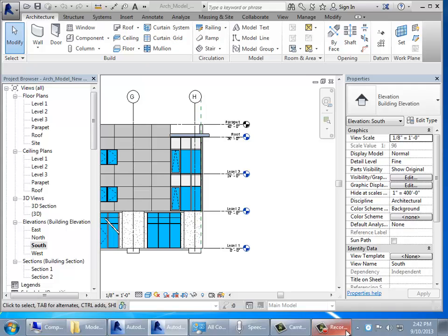I typically just leave it at 0 as a starting point, but it may be easier for you, since you're working off a set of drawings that are already referenced to a specific elevation. You put it at 100. There's nothing special about the space. It's really just X, Y, Z, wherever you want it to be. And we can move that origin point to 0, 0, 0 when we need to. But once you set it up, it's so quick. Get it set up where you want it in the first model before we start linking other models to it. The only way we get ourselves in trouble in this whole scheme is if, after other people have linked to your model, you move your 0, 0, 0 around. You just make a big mess for other people to catch up with you.